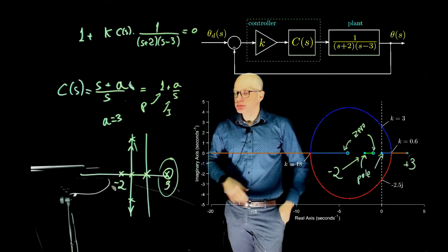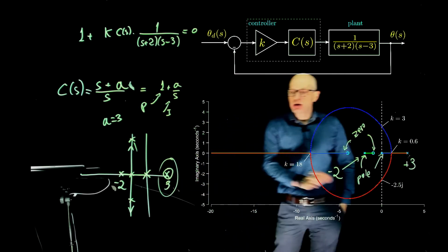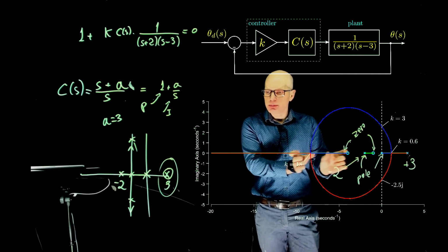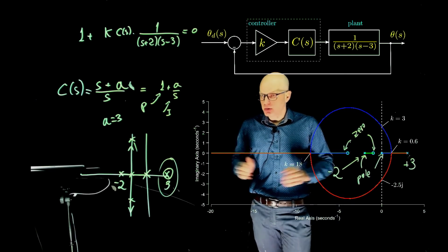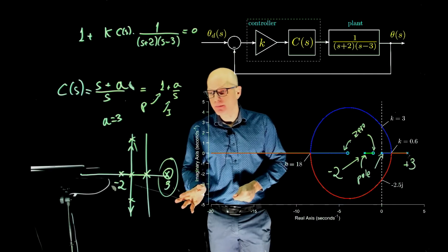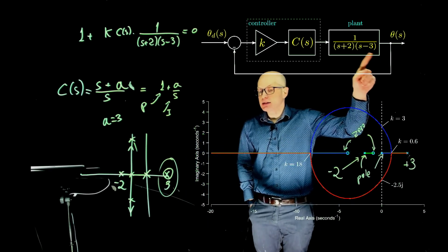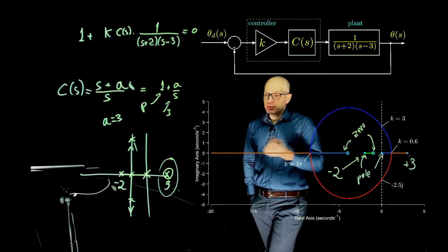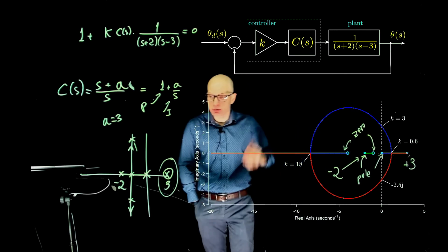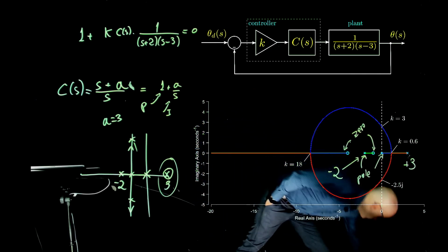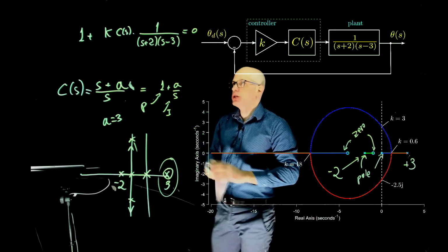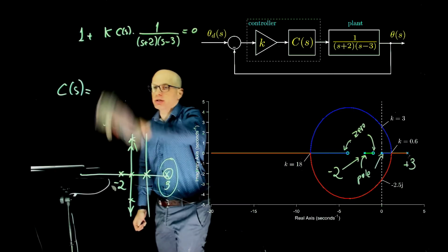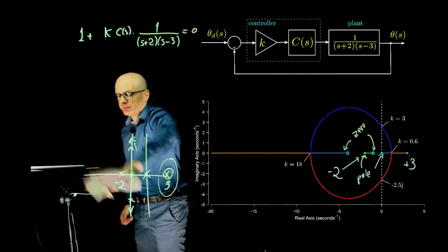It's doable, but it's a lot more complicated than something like this because here we have a lot more freedom. You don't need to be precise. You can play around with these poles and zeros. It will still be stable. Here, there is no room for that. So if for some reason we can't identify this pole, we have to go with this. Or if the system changes slightly during operation, these parameters change a little bit, and the system will not hold this configuration and all of a sudden become unstable. So the PID controller for this particular example is a much better choice.